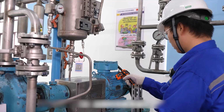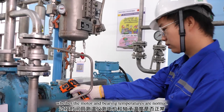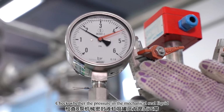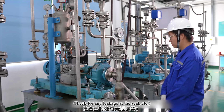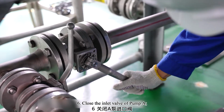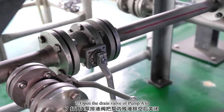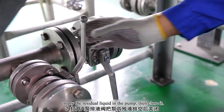and vibrations. After some time, use a temperature meter to measure whether the motor and bearing temperatures are normal. Check whether the pressure in the mechanical seal liquid siphon tank of pump B is normal. Check for any leakage at the seal, etc. Sixth, close the inlet valve of pump A. Seventh, open the drain valve of pump A to empty the residual liquid in the pump, then close it.